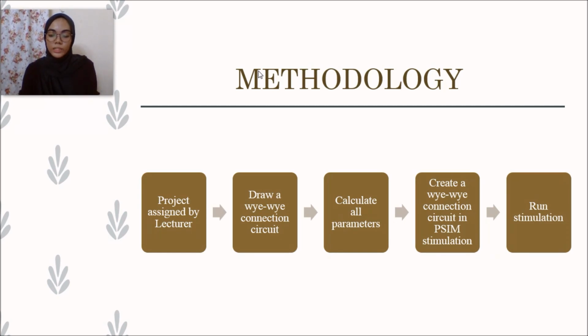And the voltage drop percentage is measured by applying the formula: V drop is equal to V supply minus V load, over V supply, times 100. And then calculate the active power absorbed by the load using the two-wattmeter method and the conventional measuring method.